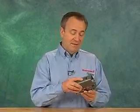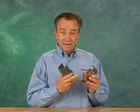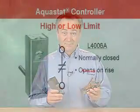Now, let's look at the device that senses water temperature in the boiler, the aquastat controller. This is a single-function aquastat controller. It has a sensor bulb and capillary tube that drives a single-pole, single-throw electrical switch. It opens its contact when the water temperature rises to the set point we've selected on this dial. This stops the burner. The switch closes when the water temperature drops past the set point and through the differential. Some controls have an adjustable differential.